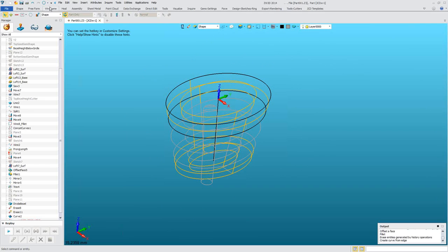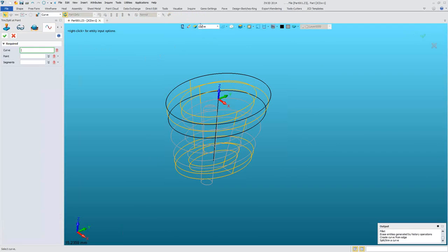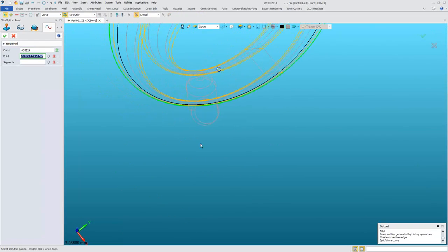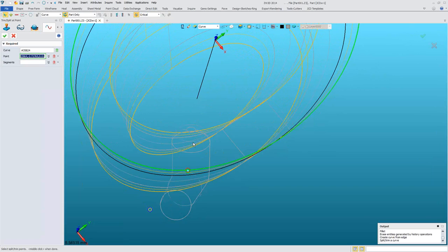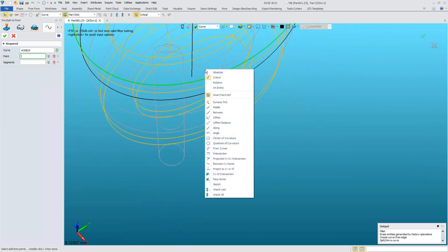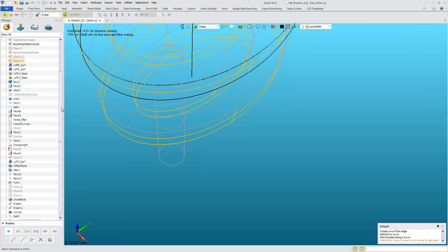So in order to do this, I'm going to wireframe, and I want to split those curves, right, entity filter on curve, at a point. Okay, and I want that point right where my shape is. Okay, I want to nail it there if it isn't. Okay, and it just may be, but I want to secure it. I'm going to right click along this here, 12.5%. I'll take that, because that's where it is, and I'll approve it.